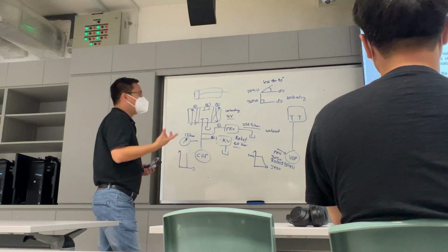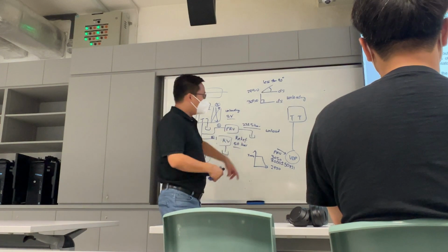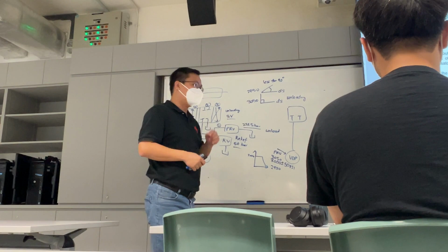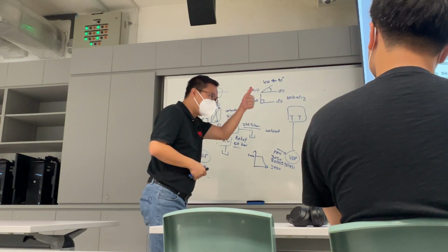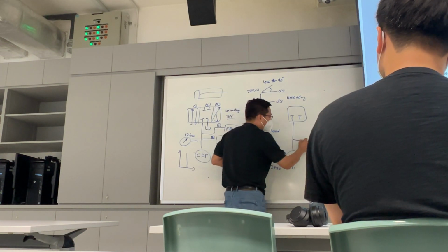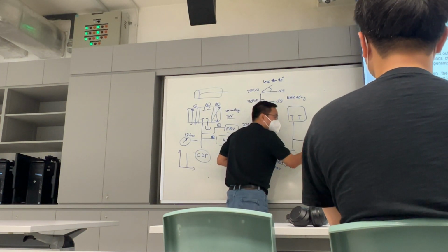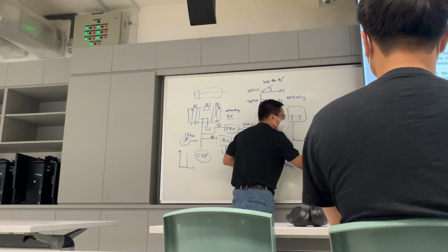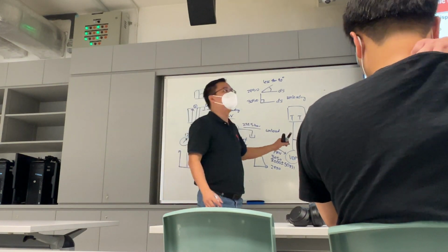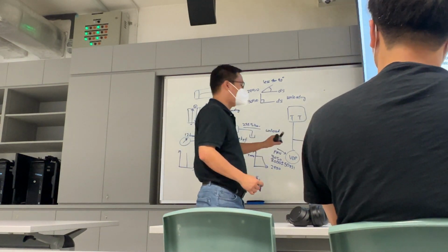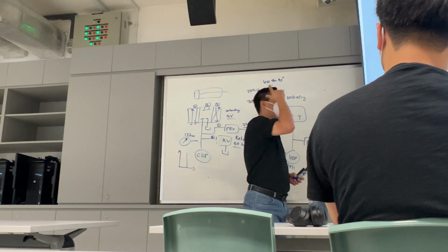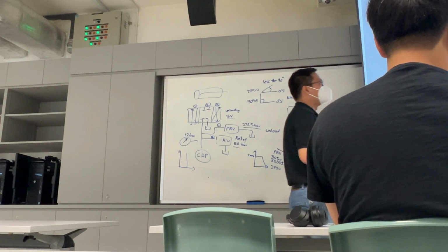Okay? Last but not least, if you allow the system to only have a variable displacement pump, there is no second line of defense, dangerous. Remember, your cabin pressurization has an outflow valve and a safety valve. So I must be a bit careful. I put one more relief valve here, and the setting is 3500 psi. This is the value and how the aircraft is designed for C-130 and F-16 safety. So they only have a variable displacement pump and relief valve. Voila, I can go with it. Okay?